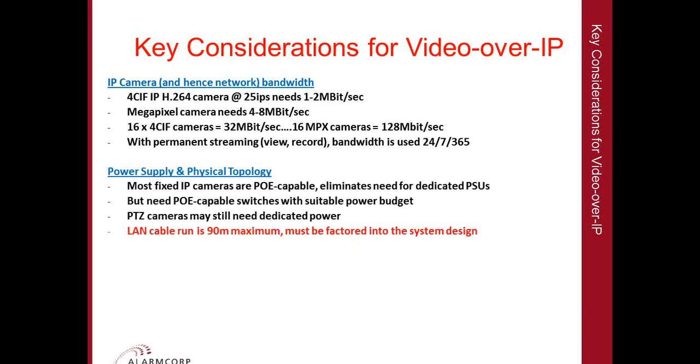Okay, when actually designing a network topology, we also need to remember the power supply. Most fixed IP cameras are PoE capable. Now the benefit of that is we eliminate the need for dedicated power supplies. However, we need to check that a PoE capable switch has a suitable power budget.